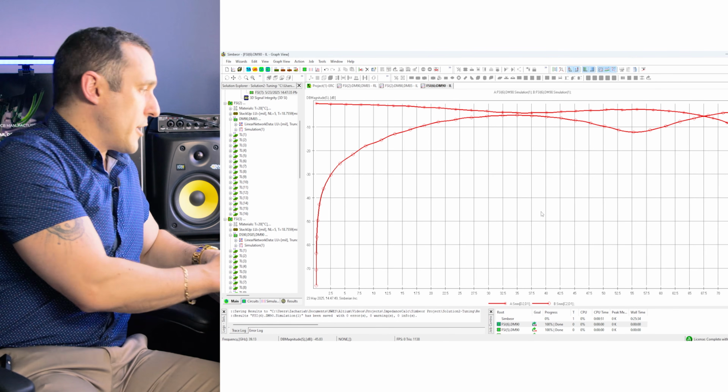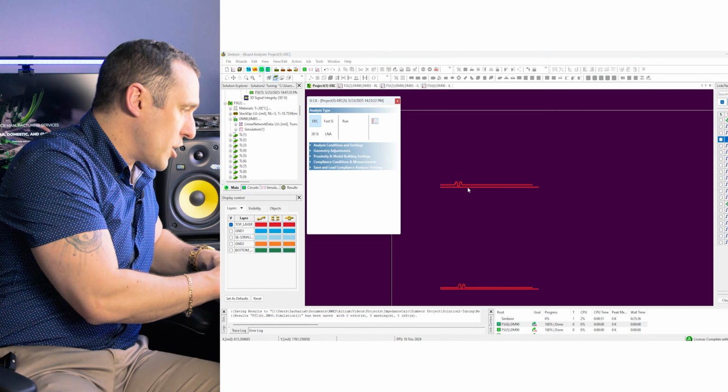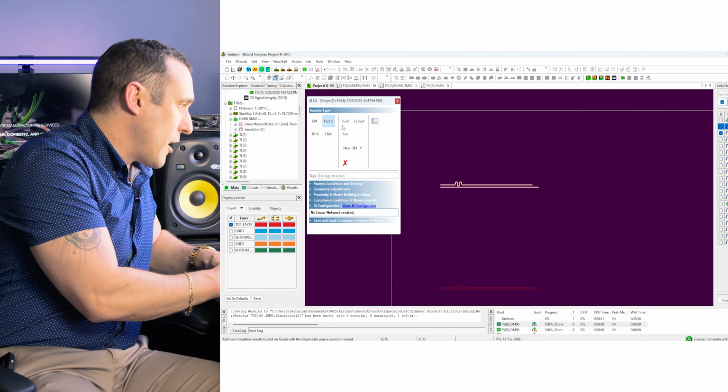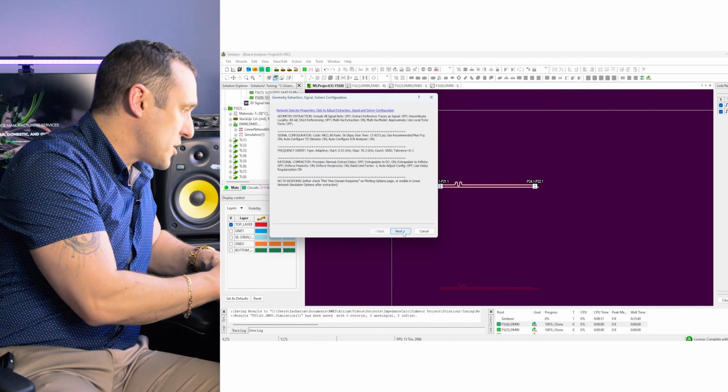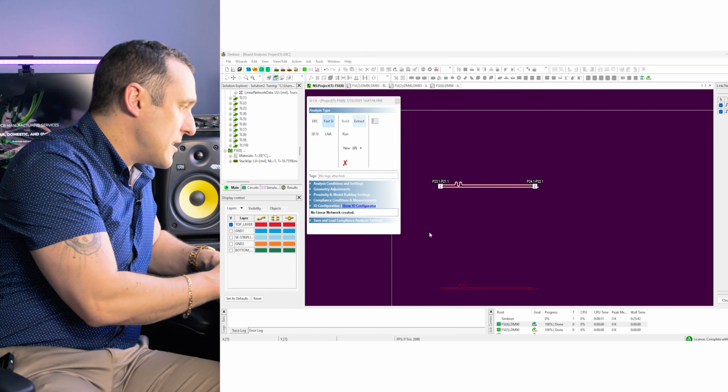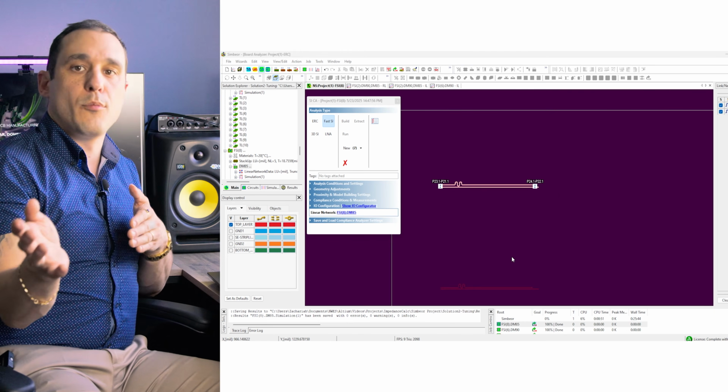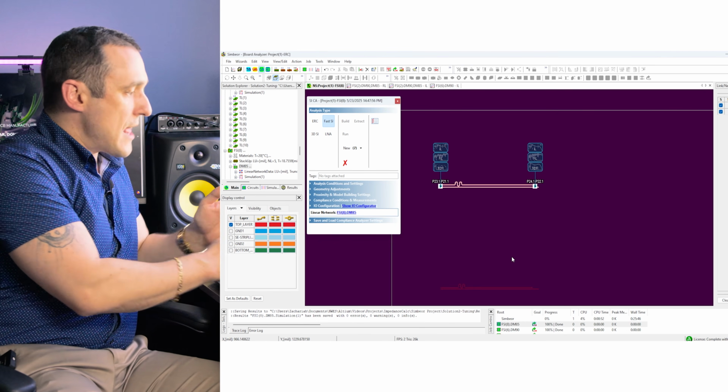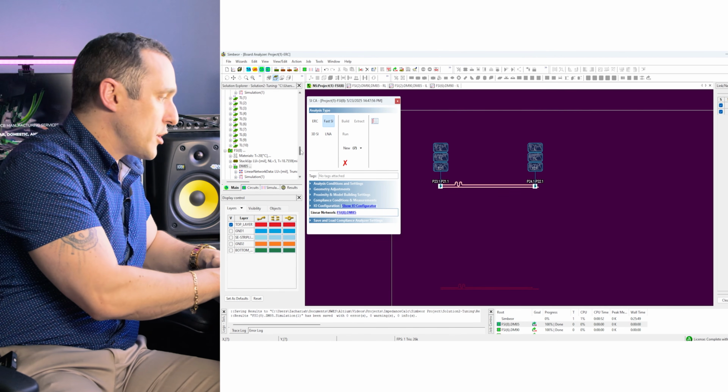Now, what about our other interconnect? What about these microstrips that started with larger spacing? Well, here I can go through, do a quick build and extract, and then I'll add in the row 4, column 1 S parameter into that graph, and we'll see what the mode conversion looks like.